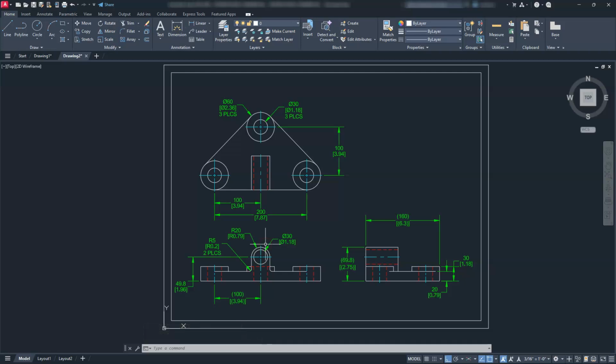All right, let's go ahead and now start working with the isometric. So remember, the first thing that we're going to do here in isometric, and this is kind of a continuation, is I also make sure that my ortho is turned on. Okay, we're going to go ahead and turn on the isometric. So this is where the iso draft is going to go. So you should see your cursor should change. And then let's go ahead and take a look at my running O snaps, since these are going to be typically the same ones that I used last time, right?